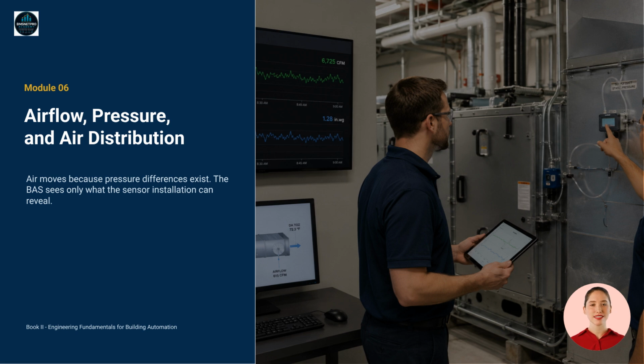Welcome to Module 6, Airflow, Pressure, and Air Distribution. In this lesson, we are going to slow down and look at what the BAS is really measuring when it shows airflow, duct static pressure, filter pressure, or room pressure. Air does not move because a screen says it should move. Air moves because the fan creates a pressure difference, and the duct system, filters, coils, dampers, and rooms all react to that pressure. Here is the field mindset for this module.